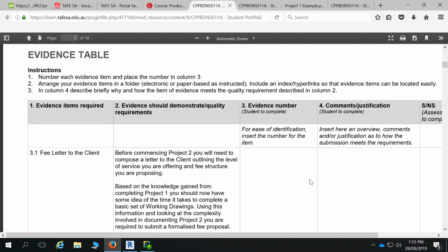If you ever go past any houses being built with Hebel, what you'll notice is there's always loads of broken bits out the front of the build, because it is very brittle on the end. So Hebel's all aerated, so the actual product doesn't have much strength in its own entity, but it's actually got mesh inside it. So it's got that grid-shaped mesh inside it, which gives it the strength. But once you get down below that 300, the grid's not really working very well, so the corners break and that sort of thing. So the last thing you want to do is have a skip bin out the front full of broken panels, which you do see unfortunately a lot on site.